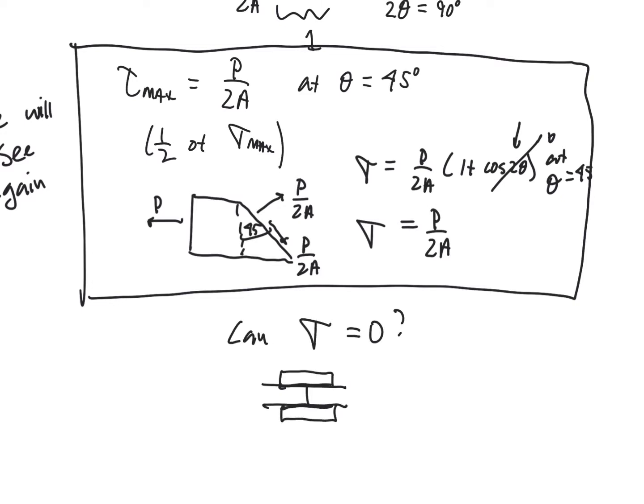And all we got was a tau. Sigma was equal to 0. The inclined plane, unfortunately, kind of breaks down, because what we would require is that 1 plus the cosine of 2 theta be equal to 0. That means the cosine of 2 theta would be equal to -1. Since I want the cosine of 180 degrees, which is -1, theta would be equal to 90 degrees.